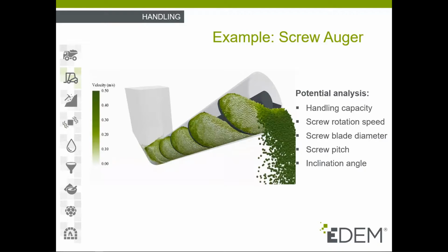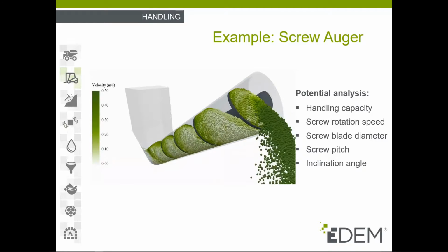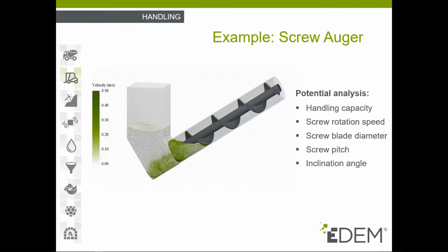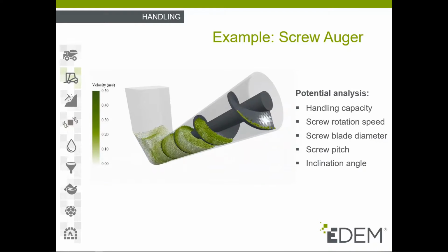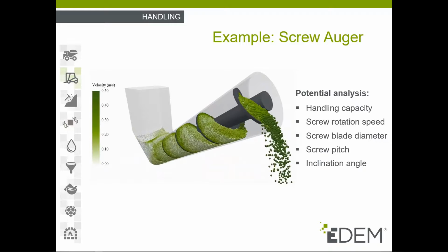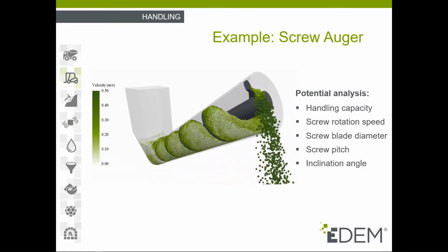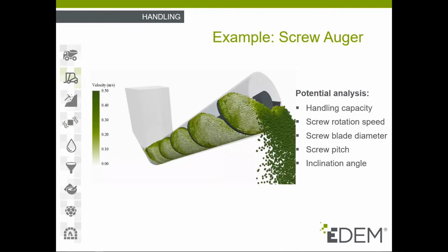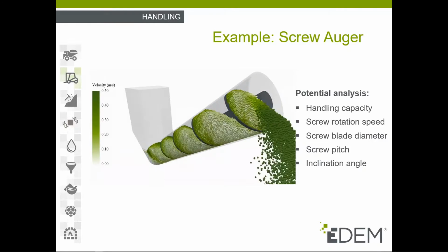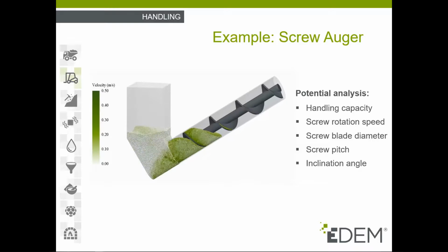This not only decides the lead angle of the screw conveyor, but also decides the split surface of the material under certain filling coefficients. And finally, you can vary the inclination angle of the screw conveyor that has an influence on the productivity and power consumption. So other points of analysis include wear of the auger, forces on the screw, and forces of particles on the surface that they fall on, for example, a hopper.